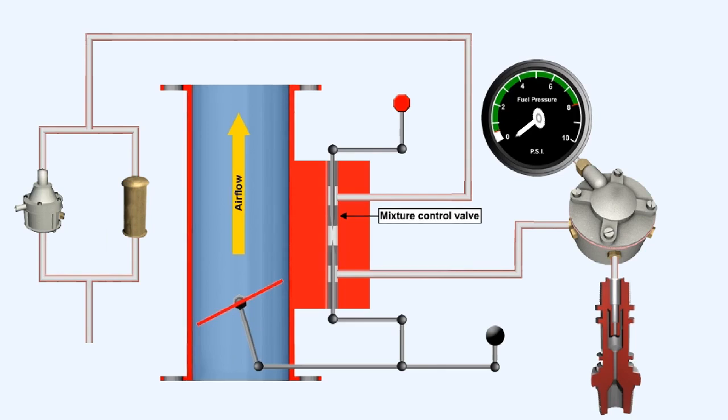The first valve that the fuel encounters as it passes through the fuel air control unit, the mixture control valve, is connected to the pilot's mixture control lever and bleeds off fuel pressure which is being applied to the fuel metering valve. Thus, the air-fuel ratio can be varied from the basic setting of the fuel metering valve as required by operating conditions. The mixture control valve can also be closed off completely, thus acting as the idle cut-off control.